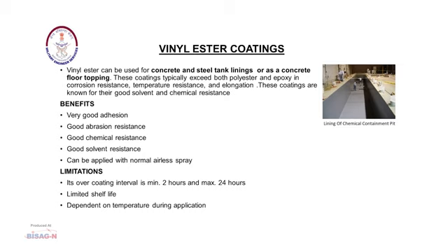Benefits: very good adhesion, good abrasion resistance, good chemical resistance, good solvent resistance and can be applied with normal airless spray. Limitations: its overcoating interval is minimum 2 hours and maximum 24 hours. It has limited shelf life and they are temperature dependent during application.